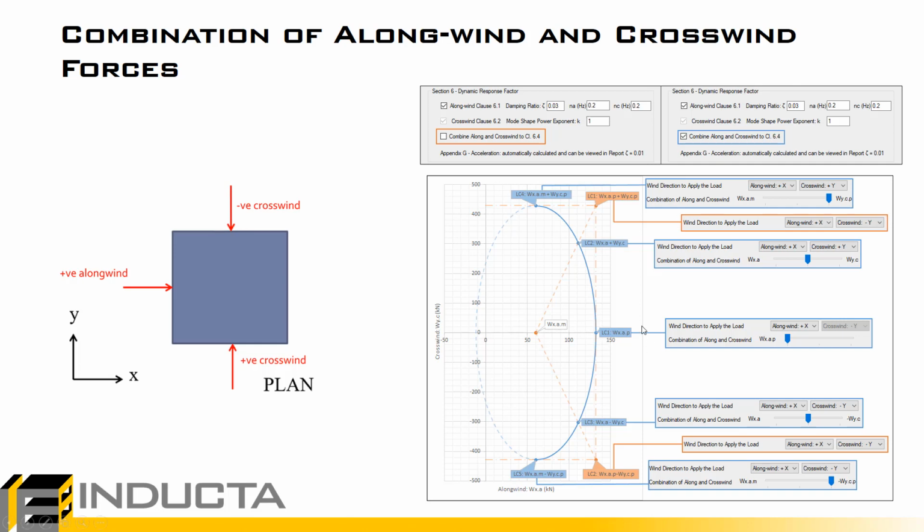When we have a peak gust wind speed, we don't have any crosswind forces. The crosswind force is generated by a constant mean wind speed. So if we have a peak value, we can assume that there'll be no crosswind forces present. That is why when we have this alongwind peak value, which is the maximum peak value, we have 0 crosswind force.